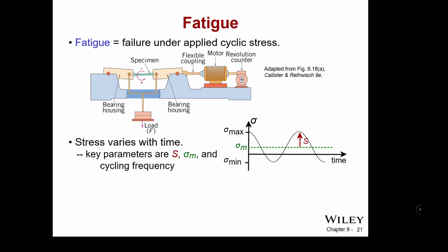This is part of the reason why the practical testing of things like IKEA furniture have the seat sitting simulator and some of these other kinds of things that are cyclic stress testing. They are testing for fatigue. How many sits does that particular design have before there is a failure point? At some point there will be a failure, but their counts are usually extremely high.